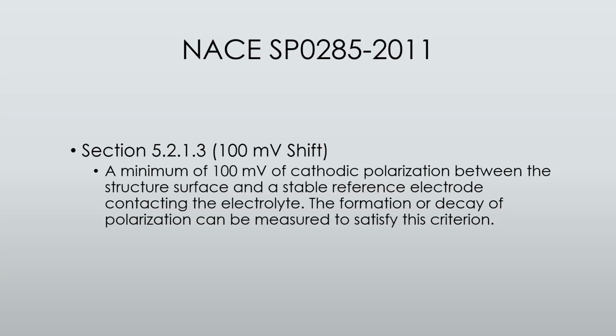And on to the third criteria, the 100 millivolt shift. So a minimum of 100 millivolts of cathodic polarization between the structure's surface and a stable reference electrode contacting the electrolyte. The formation or decay of polarization can be measured to satisfy this criterion.